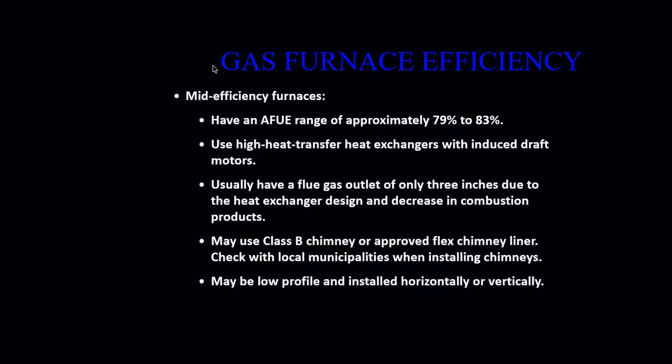Mid-efficiency furnaces have an AFUE range of anywhere between 79 and 83%. They use high heat transfer heat exchangers with induced draft motors, just like your high efficiency stuff. They usually have a flue gas outlet of only 3 inches due to the heat exchanger design and decreased combustion products. They are also used on Class B type chimneys or approved flue chimney liners.